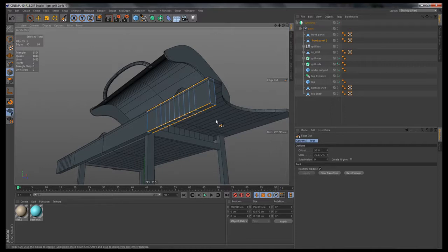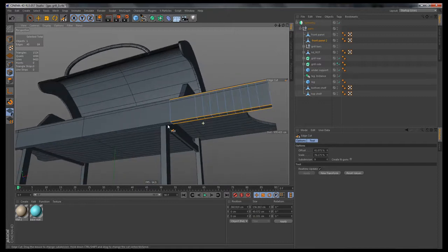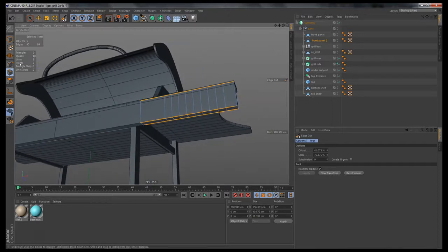And I'm still holding the mouse button. I have not released, but I'm releasing Shift and now pressing Control and holding that, and you can see that's allowing me to offset all those cuts. So we'll go about there, and then I release everything, and I am locked in, good to go. So now how do I get that gentle curve?